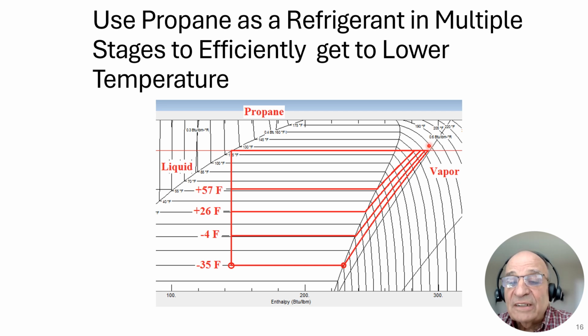That's all going into this four-stage compressor at different points in the compressor, and it sends the fluid through the aftercooler condenser and then through the JT valves to the various pressure levels.